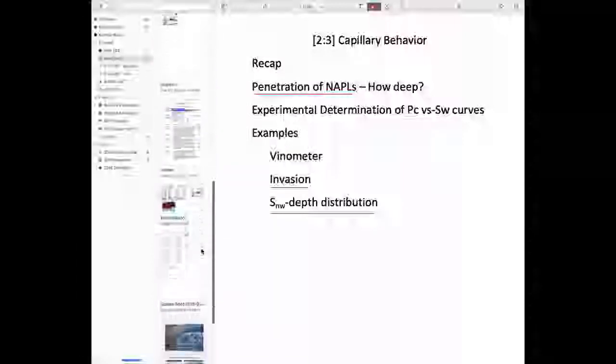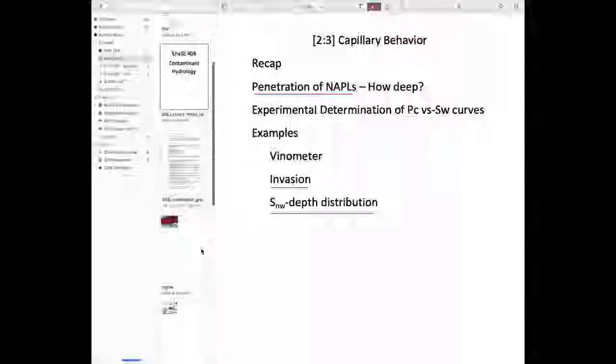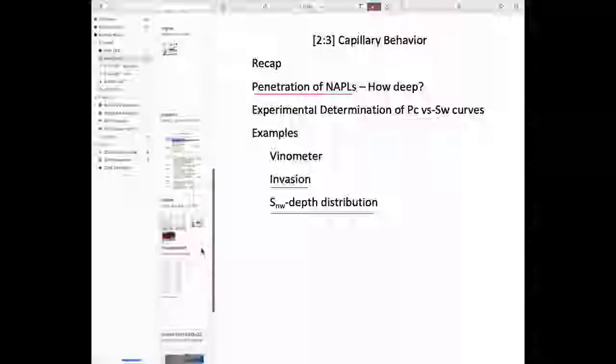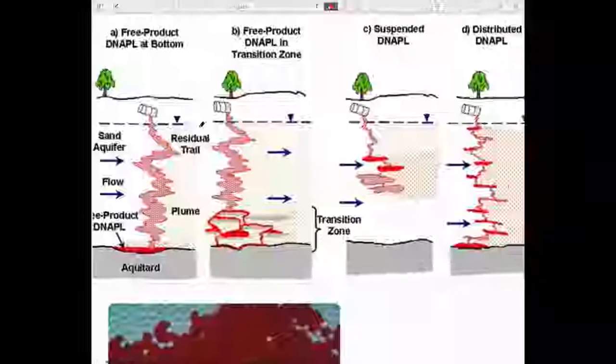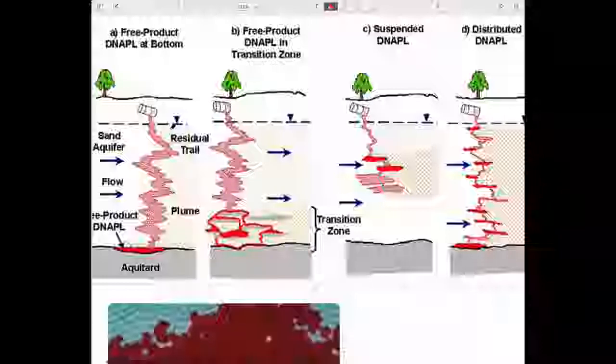And that's not badly illustrated by this figure, which we've seen a number of times, right? This geometry. These different architectures that we have for a NAPL: it zips across the water table. It's stopped by an aquitard for sure, because it can't get into the pore space. If it meets some low permeability lenses that have small pore spaces on the way down, then it gets hung up on these and builds puddles on top of them that leak off either side.